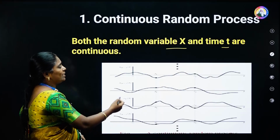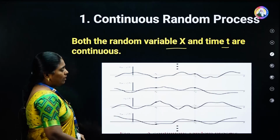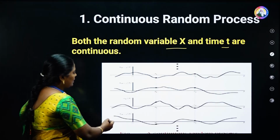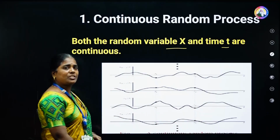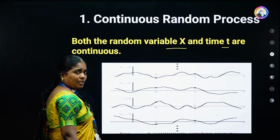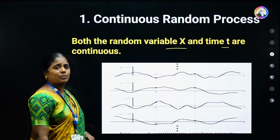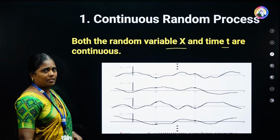Let us see the plot for the case of the continuous random process. As I have explained earlier, on the x-axis we have the time, on the y-axis X(t, s1), X(t, s2), and so on. Here you can see the diagram we have drawn, like a random sine wave, which changes continuously. That means the time t is continuous. At the same time, the corresponding values on the y-axis are also continuous, isn't it? So that's why both the random variable x as well as the time t are continuous in this case.